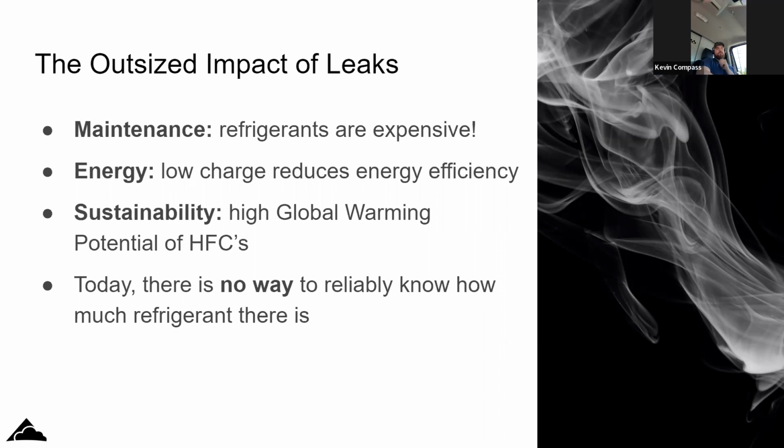I mean, it really depends. Some leaks are easy to find. Some days you may walk into a customer that drilled a coil with a forklift, and that leak finds you. Or some days you'll walk into a machine room and something's spraying. It's easy. And then some days you have a nightmare leak that only shows its face when something's in defrost. So it all depends. It could be an absolute horrendous day looking for it, or it could be an hour or two you're in and out. Makes sense. All right, let's go to the next slide, Turner.